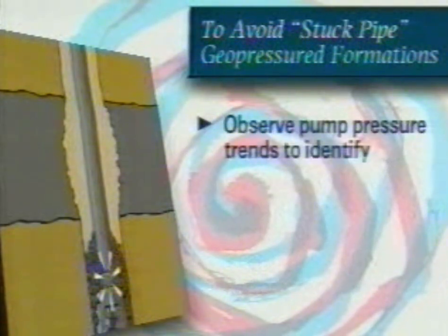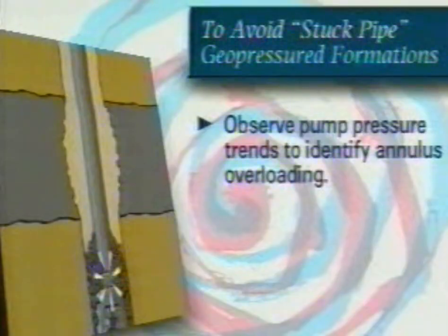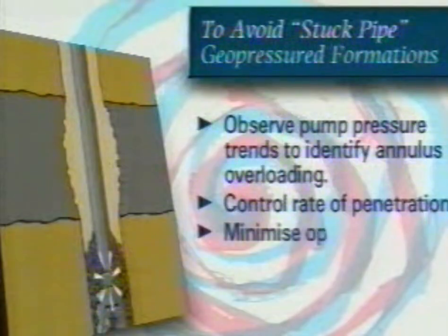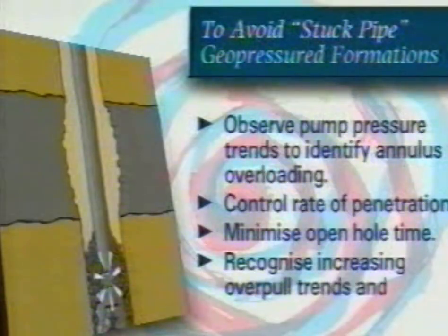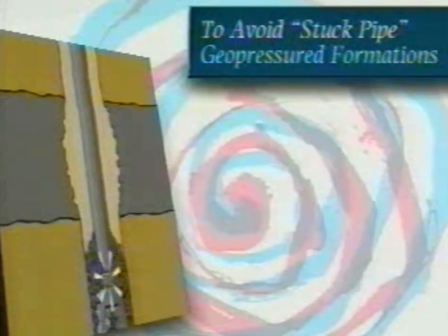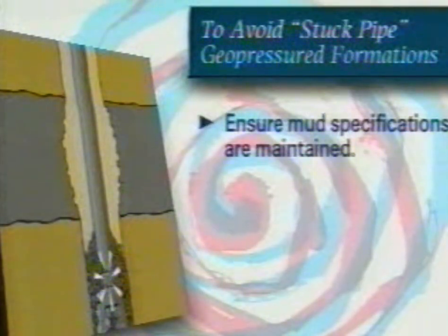Observe pump pressure trends to identify annulus overloading. Control the rate of penetration. Minimize open hole time. Recognize increasing overpull trends and stop drilling until the hole is clear. Ensure mud specifications are maintained.